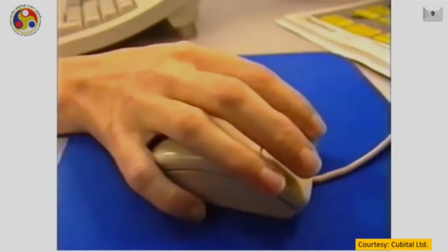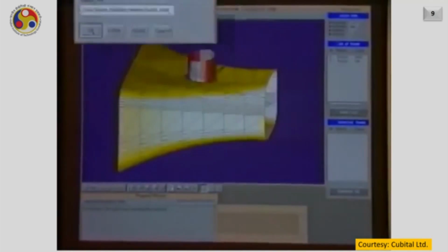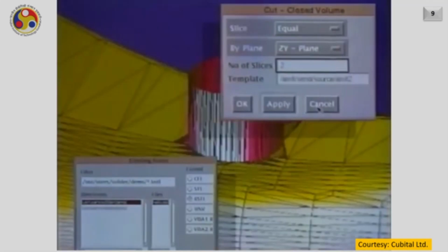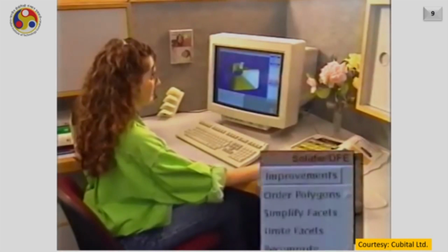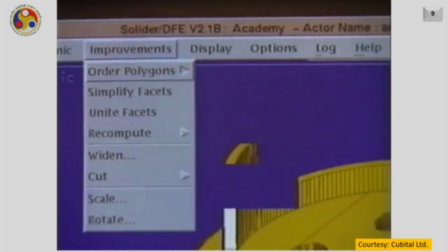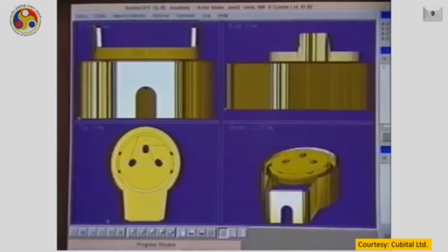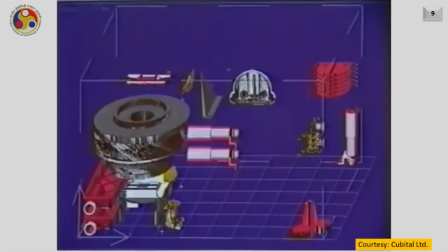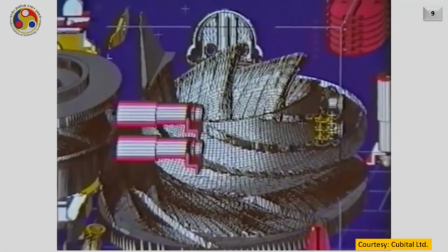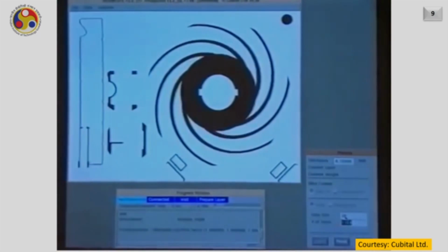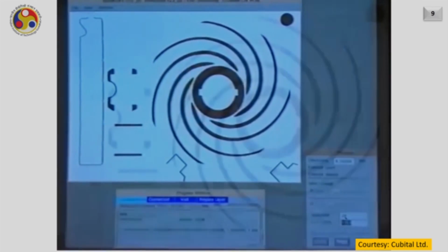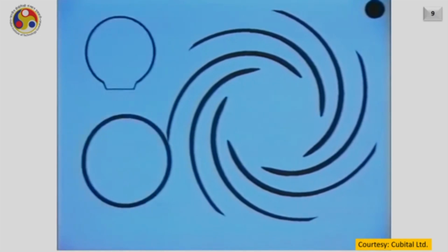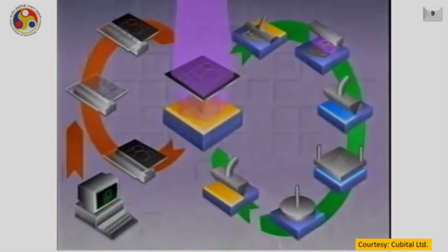So, the first step, like in other additive manufacturing processes, is to create the CAD model and convert it into the STL file. And of course, then we do the slicing of the products which we are making here. This slicing data is used to create the photo masks. This is the process cycle which I just explained to you.